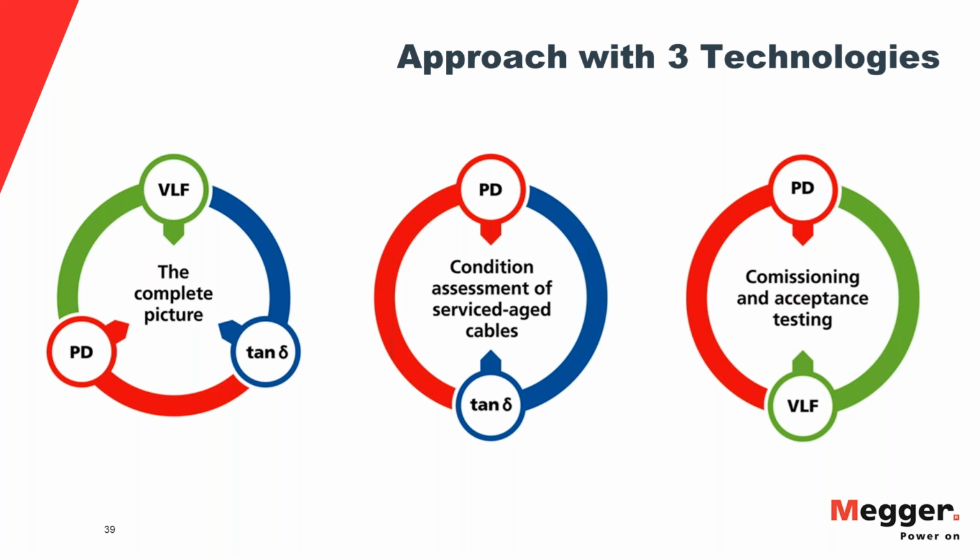Yeah, exactly as Jason said. Don't confuse things. Yes, the insulation resistance test is a classic DC test, but typically most people just do it for 1 minute, right? And that's it. And then you discharge and you're okay. When we say DC testing on cables, there were standards for that. And DC was the standard method for the PILC cables, and in these tests, they were talking about 30 minutes testing time, and 4 to 6 times operating voltage. So that is a completely different thing than hooking up a little insulation resistance tester and just measuring some gigaohms.